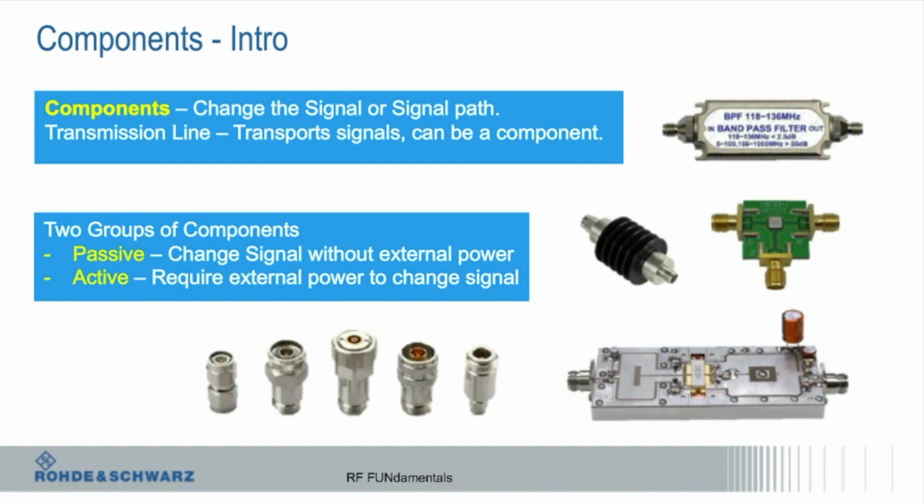Question? That question of calibration before, now that you're pointing it out, that's the most important part. Every time they make a new connection, they should examine the connectors before they insert, because if that pin is damaged, you're absolutely right, you're going to get bad readings. And I do have a couple slides on that.